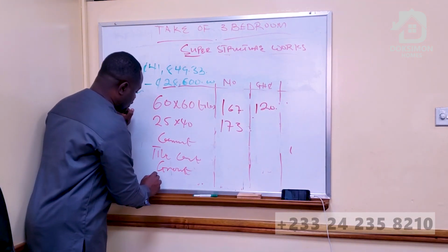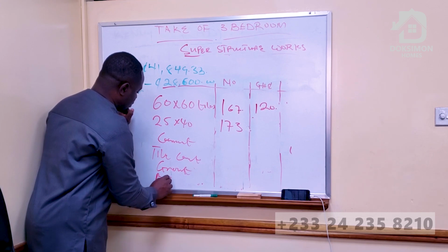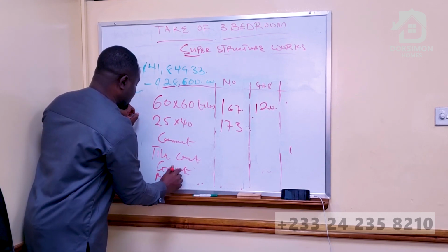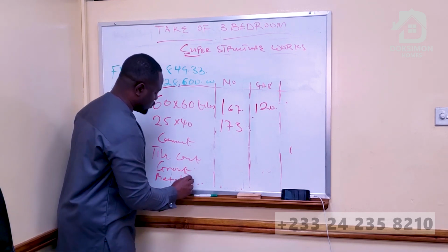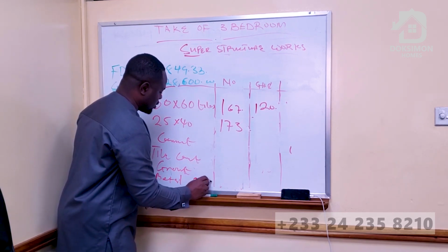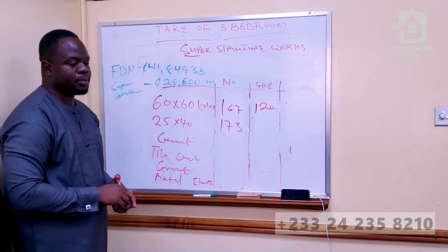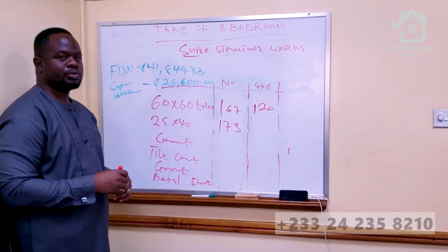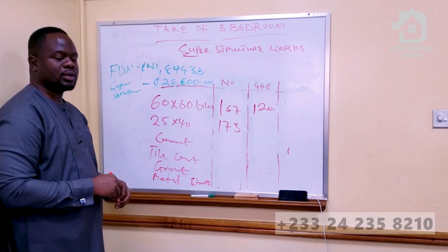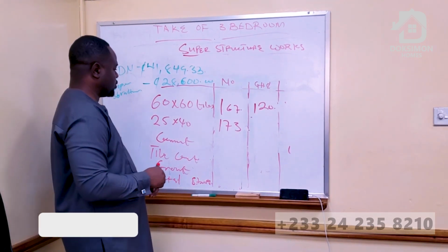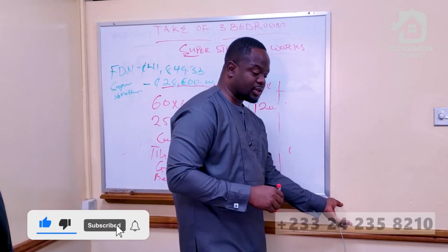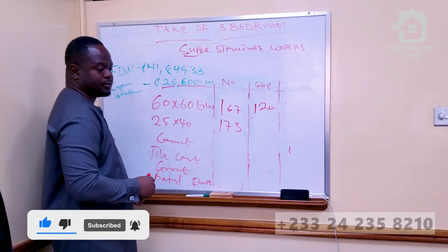But metal strips help the tile stay within a defined course, and it does not cut people. So wherever we need a metal strip to be introduced appropriately, please do, and help your contractor understand that it's very important to you. You should put them in.